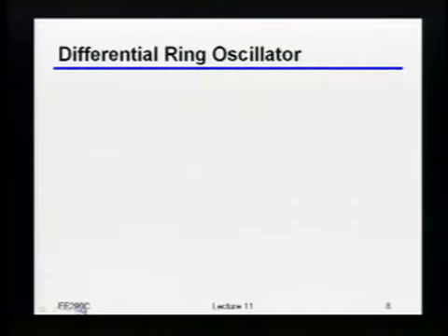One is just getting the differential phases like we just talked about. But even independent of that, sometimes you'll want something like a multi-stage differential ring. As an example, another fairly common technique is to run the link at what's called double data rate, meaning that on both the rising edge of the clock and the falling edge of the clock, you try and grab data, right? But if you think about what it would take to also recover the timing information, that would mean you'd also need a quadrature clock, right? Because this would end up being half a bit time away, let's say t-bit over 2 if you do the quadrature clock there.